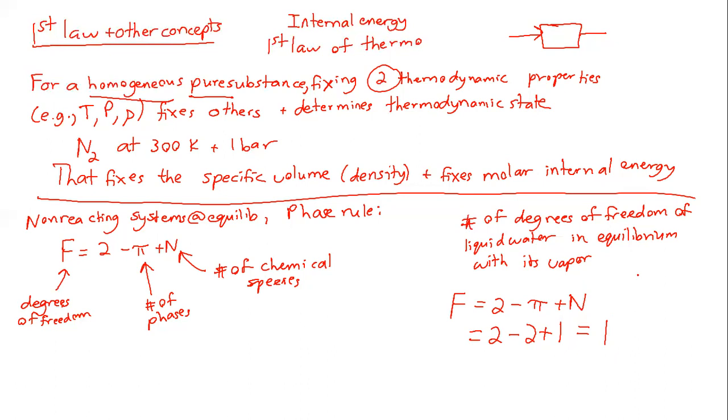That's really important because when people are talking about pressures of steam for heating, that might sound off base at first because you think, pressure isn't what heats. Temperature differences are the driving force for heat transfer, not pressure differences. Why does this matter? It's because the steam is saturated. If you specify its pressure, then you have effectively specified its temperature because of this phase rule, meaning that now you have specified the driving force for heat transfer, which is the temperature.